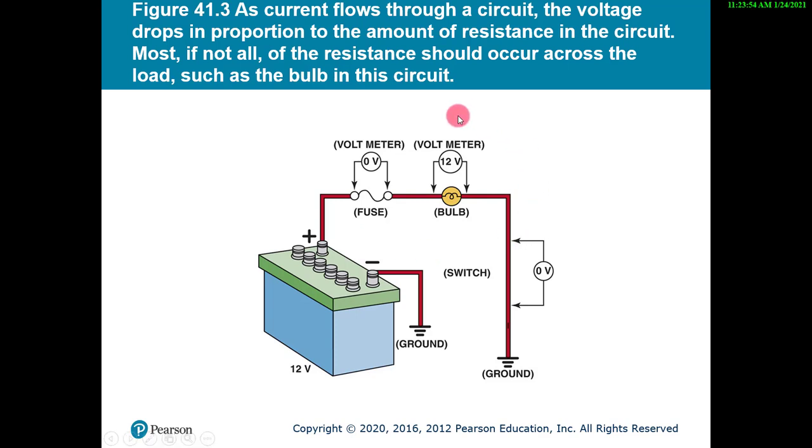We do want all of the voltage to drop across the load or the resistor, right? So as the power flows into the bulb, the power side flows into the bulb, the ground side flows out of the bulb, the difference in pressure on either side of the bulb should be what the applied voltage is. And that's the applied voltage here. Likewise, if I were to measure the ground side of the bulb and put my other lead down at the chassis where this wire is connected, so essentially what this multimeter here is measuring, I should see negligible voltage drop, or in other words, 0 volts.